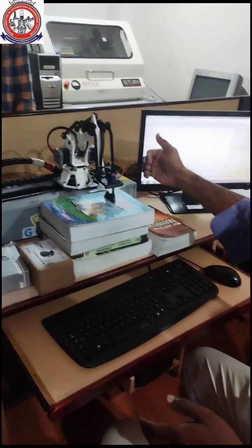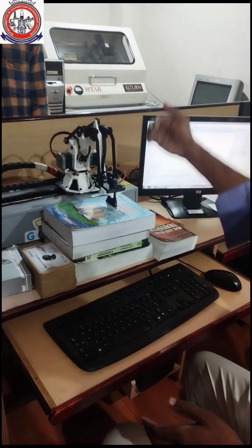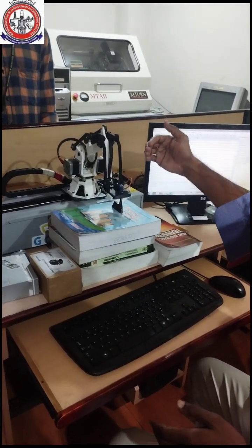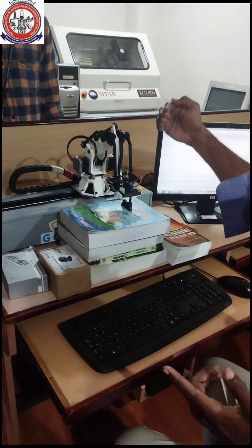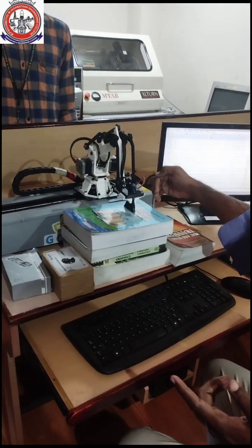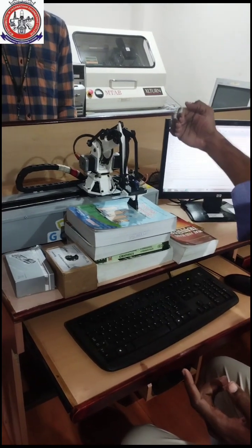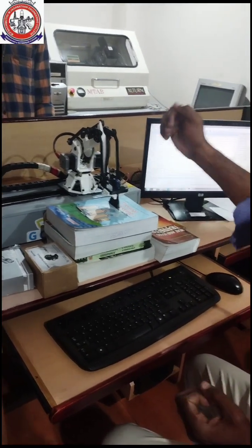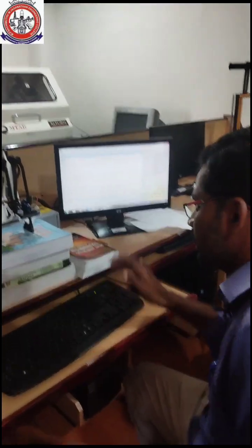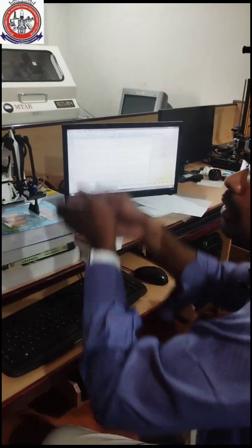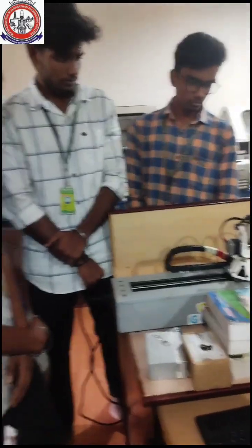Now if you raise the z axis, the object will be lifted. If you recall the x minus in the first step, going from the home position to the object position gives a minus symbol. Likewise, you lift the z axis with minus 60. If you give G1 Z minus 60, the held workpiece will go up. We will give an enter.